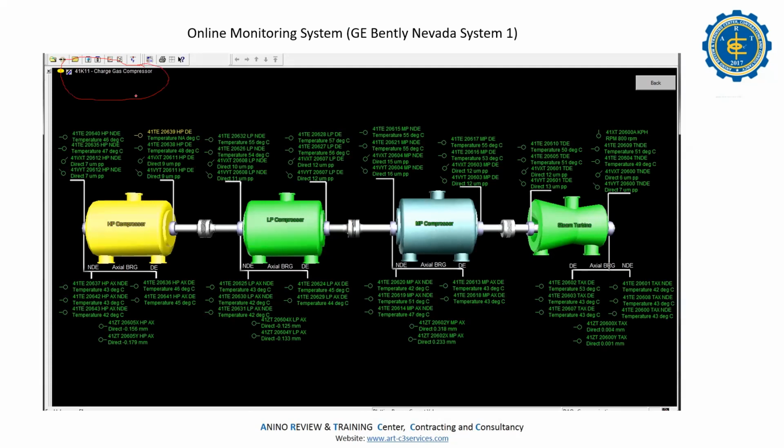So in one compressor, you have a steam turbine. The steam turbine is the driver. Then we have the compressor, we have HP and LP, high pressure and low pressure. If you monitor daily and you see this yellow, it means there's a problem here. Yellow alarm. Then you can check it. Green, good. Then you can see the vibration monitoring, the probe, the proximity probe.